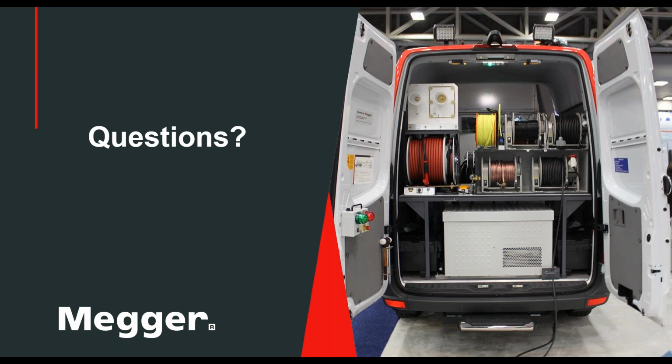And when you have a low voltage cable that has an armor, it can serve, so to speak, as a shield. So I can now flash over to that armor, and I have a ground again. So I can use some of the fault locating methods for medium voltage cable also on an armored low voltage cable.